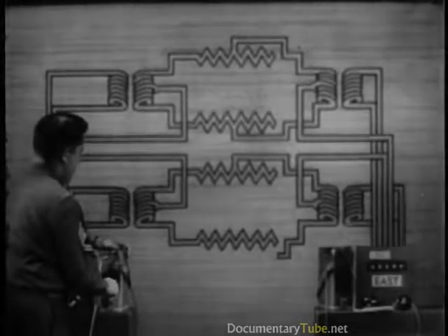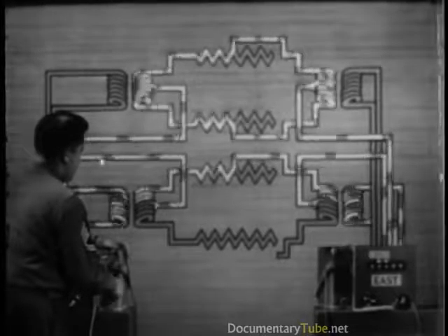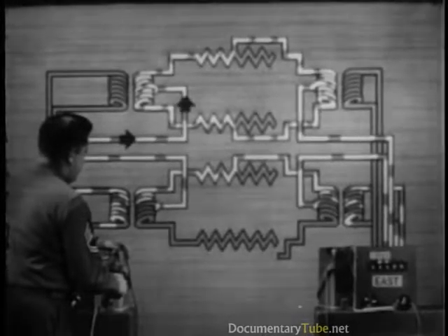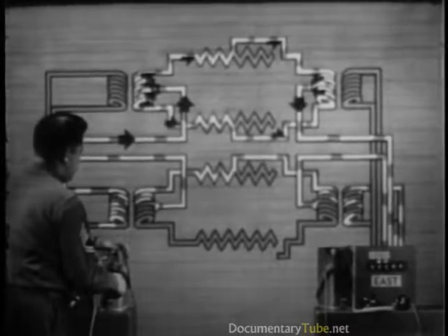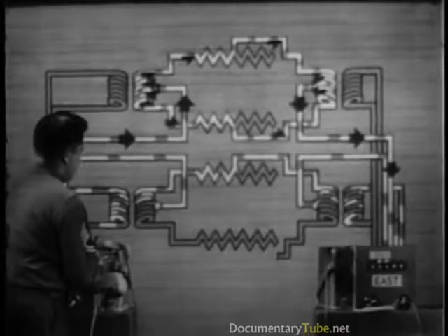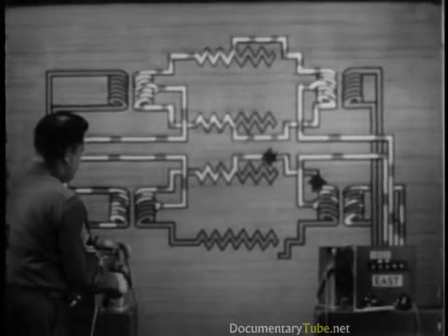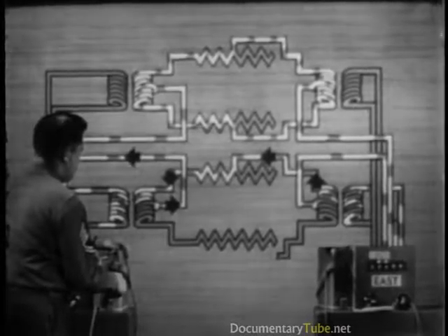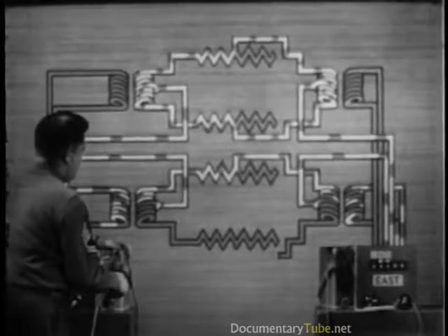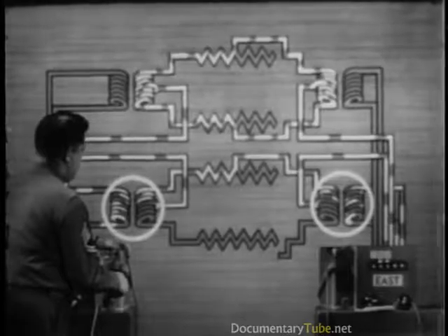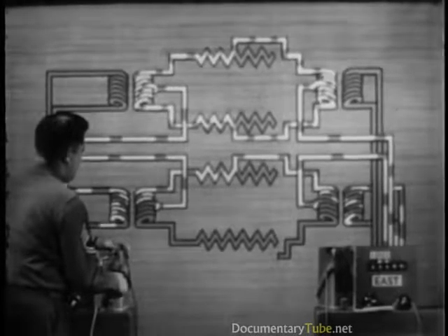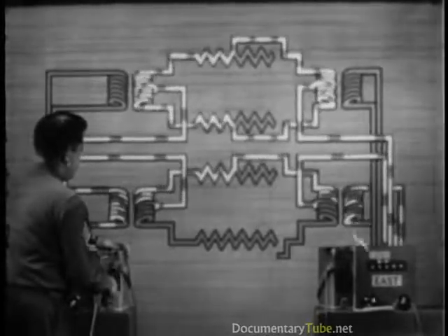We will ring on the phantom first. The phantom current travels through the unbroken side circuit in the usual way. But in the open side circuit, all the current goes through one wire. This induces current in both the other windings of both repeating coils. In the faulty circuit, it produces interference.